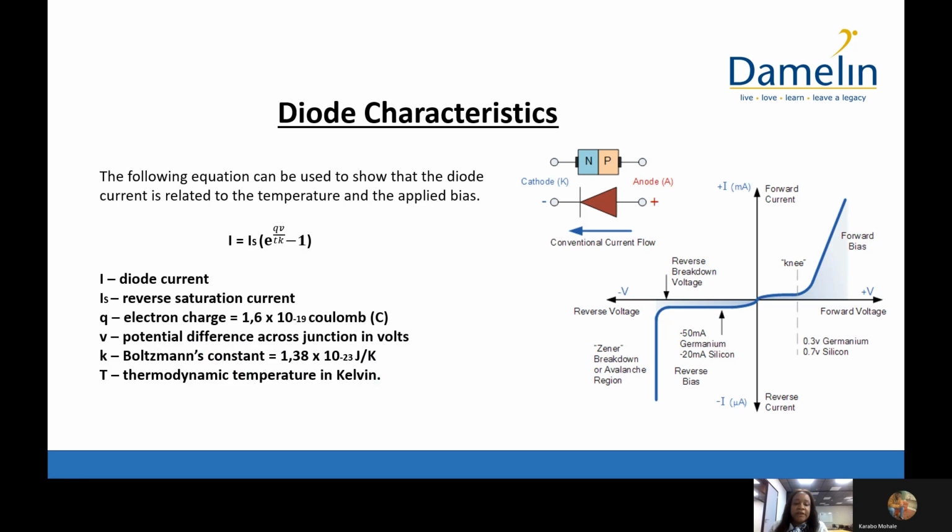Okay? The characteristic curves, you can see this is a very important characteristic curve of the diode, which is the p-n junction. It's known as a component, the diode. This tells us basically how it behaves. We have the forward biasing stage, which connects the positive to the P and we connect the negative to the N. And this tells us that the current will flow easily. You see there's a positive current, it's milliamps, but it flows easily.